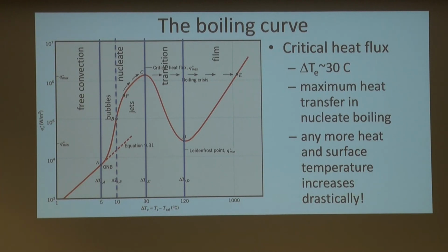When you do that, look at this. If I were to put in this experiment here 10 to the 4 watts per square meter, I would have something like, I don't know, 6 or 7, my excess temperature would be 6 or 7 degrees. You see that? Now, if I were to put 10 to the 5 watts per square meter, I would have an excess temperature of 10.